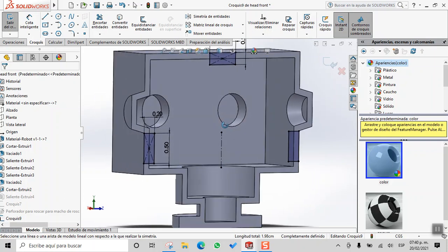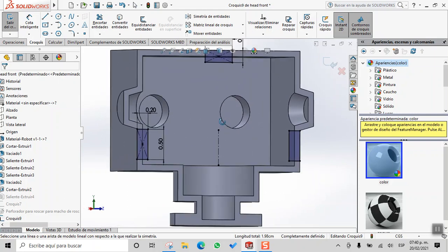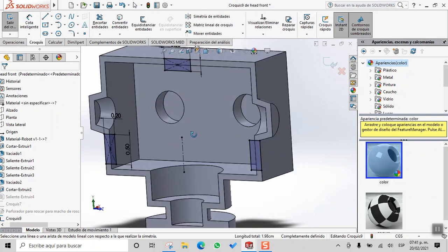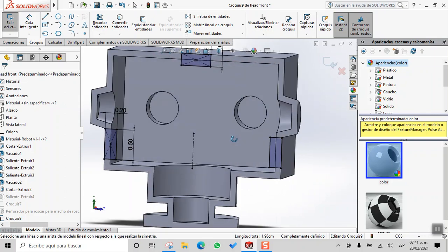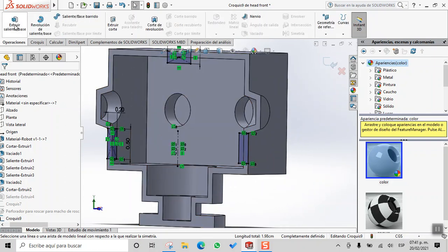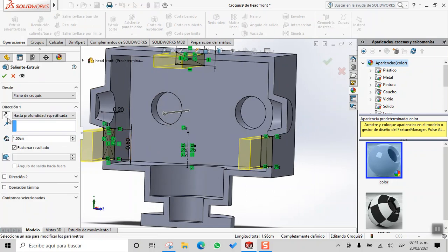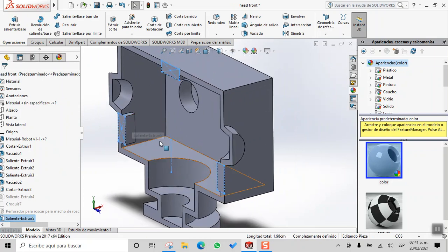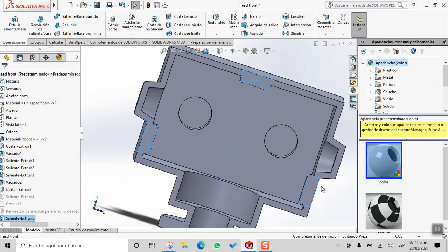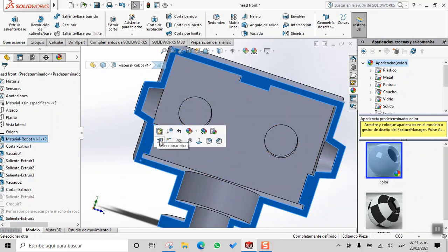and actually I believe to hold it in place, we will need to do an extrusion backwards, right? So features, extrude. Now let's change the direction and say 2 millimeters. Okay, so this part will be set to this point. Now we can use this same reference point to create the front part.